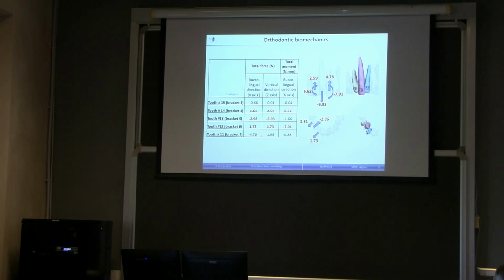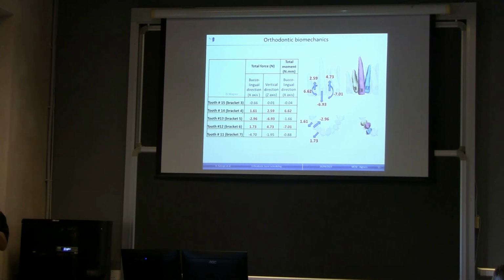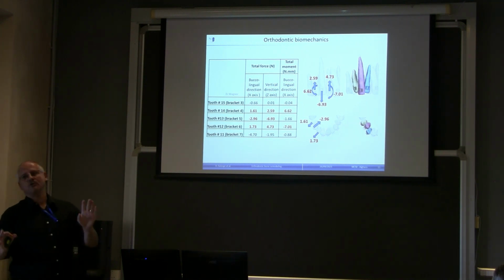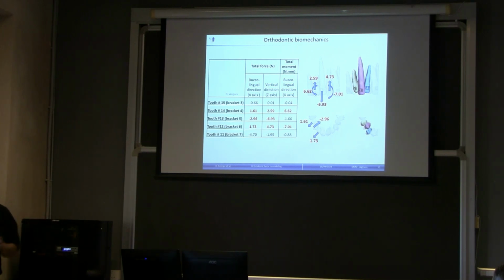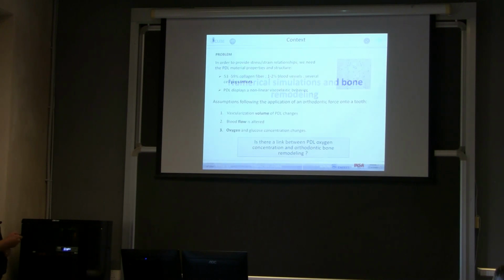But eventually, in a simple case where we are not outside of the range of working, we were able to quantify using this static equilibrium the forces and moments that were applied onto the teeth by the wire. Once we are here, we have the input, which is already quite good. We're happy to have the input. But then we want to know how the tooth moves inside the bone. So we need to look at the other part of the work, which is the numerical simulation and bone remodeling.